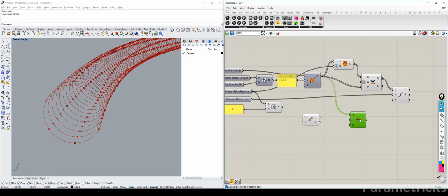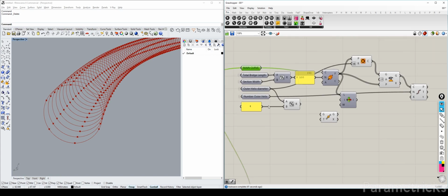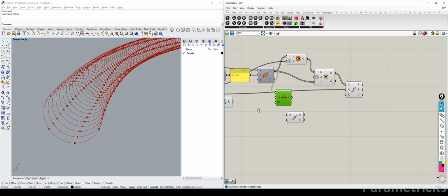Actually, I can maybe make a point XY point construct. It's called the new ones, and we can actually say, is that no? That's not a good way to do it. We have to do it with this. We have to use whatever geometry is already built, so that they can always go along with it. In the event that this main curve is not sitting on this z direction, but somewhere much higher, then that will mean that the number here will not make sense anymore. So we have to use this one instead.